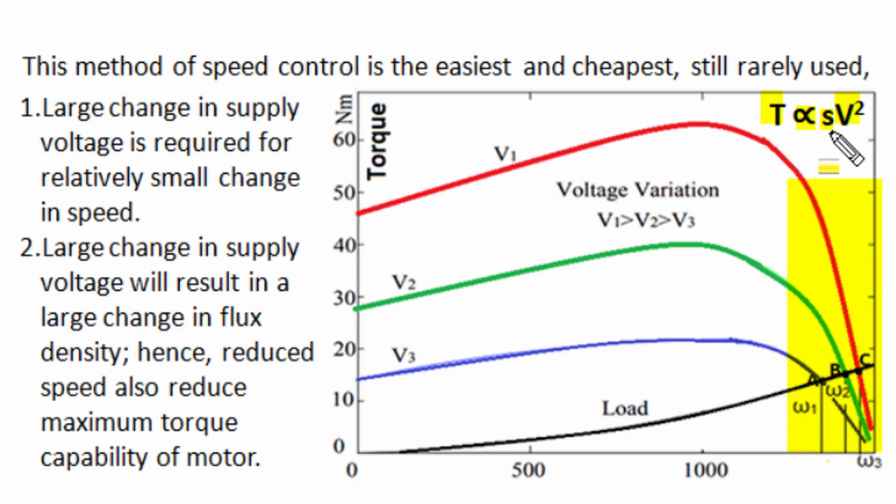So to make a small amount of change in operating speed by slip, we have to make a large amount of change in applied voltage, and large voltage change results in very small change in speed, and the maximum change which we can produce is up to the speed of maximum torque. Beyond that we cannot make change in speed, and for economic design of induction motors, the slip of maximum torque is only 5 to 8%. So by change of voltage, if full load slip or slip of maximum torque is small, we can't make a good amount of change in speed by this applied voltage control.